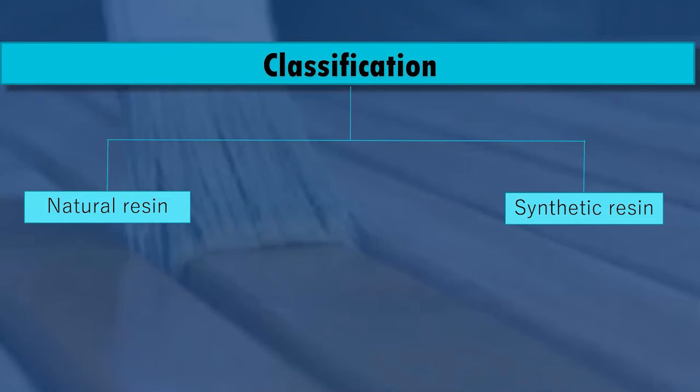So let's see. First, varnish is classified into general classes. The first is natural resin and the second is synthetic resin. For natural resin, the varnish is a solution of natural resins that are secretions of plants. Among these natural resins are damar, copal, and rosin. These resins are synthesized by the plants to form a resinous substance in varnish. The varnish is produced by heating the resins, adding natural oils, cooking the mixture, then diluting with solvent. This varnish may take 3 to 4 days to harden and it forms a yellow tint.